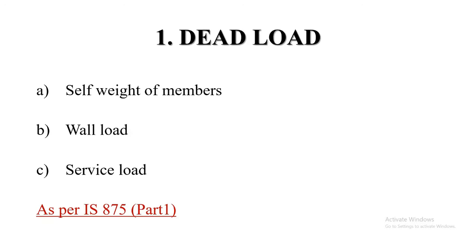We don't have to calculate the self weight. In some software, like STAAD, we have to calculate the self weight, so it's a bonus that we don't have to calculate it here. Now next comes your wall load. Wall load we have to calculate, and what are the factors by which we can calculate the wall load? They are your wall thickness